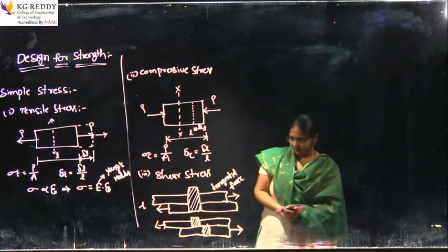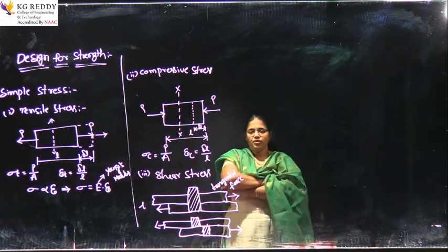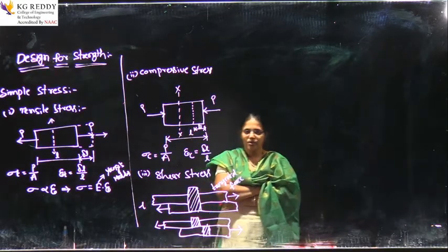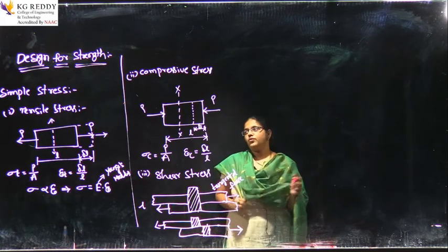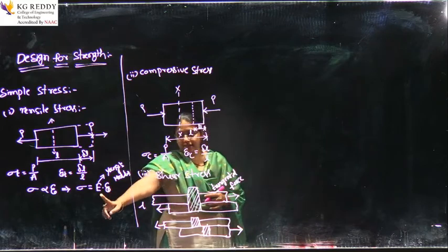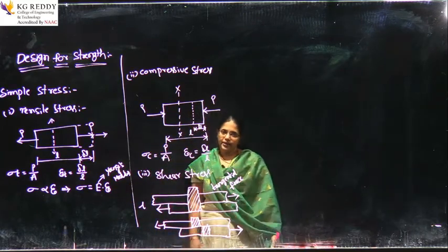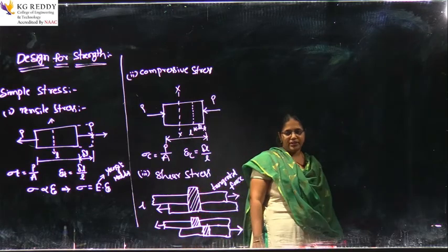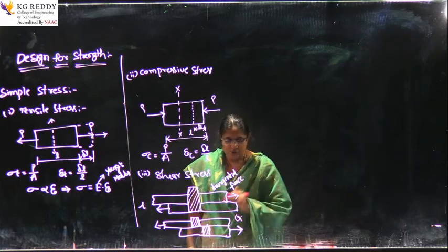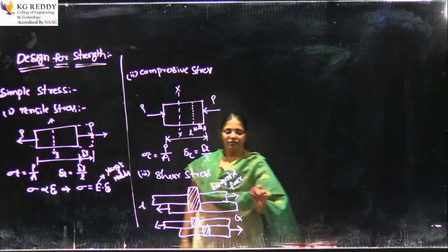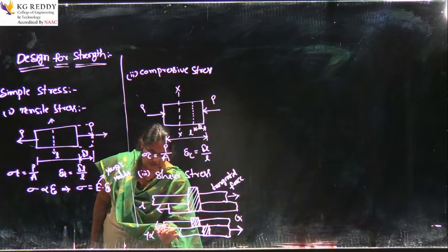So, whenever I am applying this type of force, shear stress tau, we will always get the shear strain. Here we represented Young's modulus of elasticity, and similarly we can identify the modulus of rigidity, which will be represented with letter G. Modulus of rigidity is nothing but the shear stress being directly proportional to the shear strain.